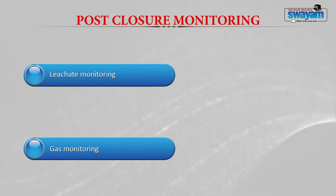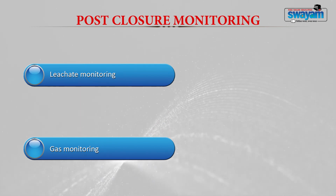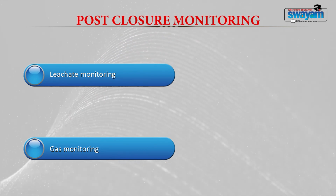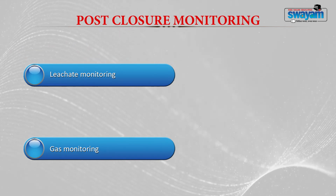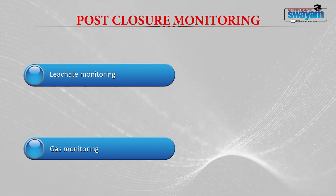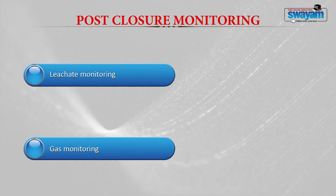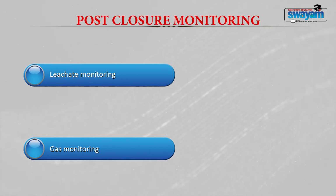Before constructing a landfill, you have reference data of water quality analysis, and afterwards you can measure and compare the water quality with the reference, and see whether there is any leakage, breakage or rupture in your liner material, and whether the leachate is entering and contaminating your groundwater. Then for gas monitoring, you should have a gas monitoring station to find out if there is any excess leakage of gas from the landfill cover.